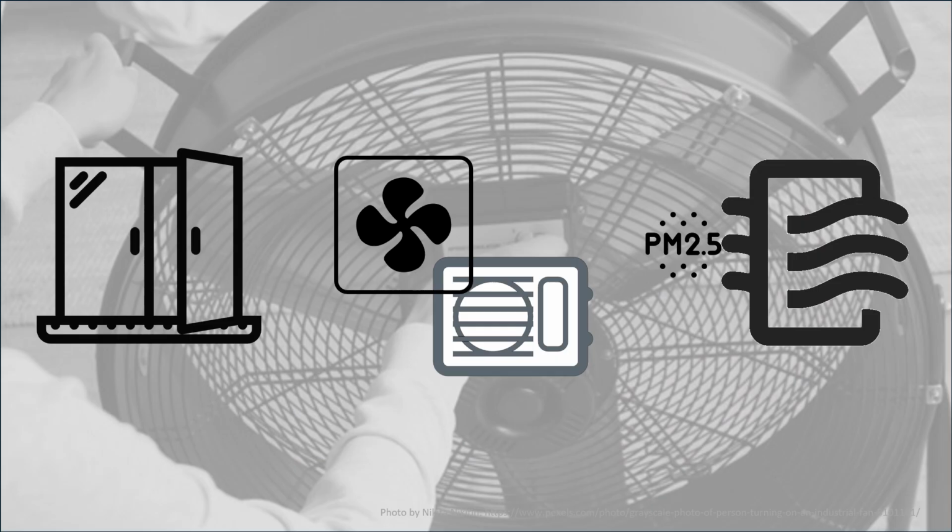To improve ventilation and hence indoor air quality, we could be using simple measures like natural ventilation based on windows and doors. And this is particularly useful when the outdoor air quality is good. If the building has a mechanical ventilation system, then we need to make sure that the system is being maintained regularly, any replacements needed are being done, and it's being kept clean. Where possible, the filtration in the mechanical ventilation systems can also be upgraded. If further required, we should also consider the use of portable air cleaners inside specific rooms, depending on the type of activity and how many occupants you have in a room.